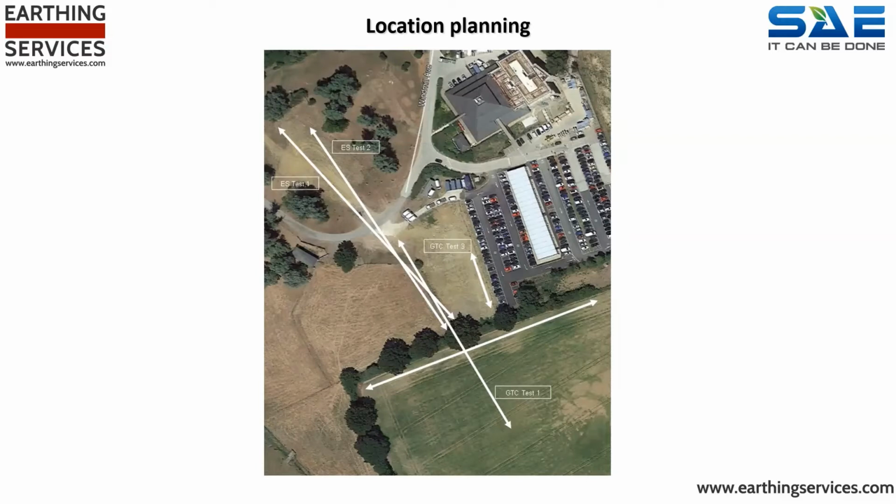A single run or collection of soil resistivity data requires approximately 170 meters of uninterrupted open land, soil type ground mass. And this enables the engineers to assess the electrical resistivity attributes of the ground to a depth of over 50 meters. It is usual that the lower the depths, the more stable and generally better the electrical resistivity performance. In the event that less land is available, it is not uncommon to do shorter and therefore shallower soil resistivity surveys. However, this results in a less exhaustive data set.